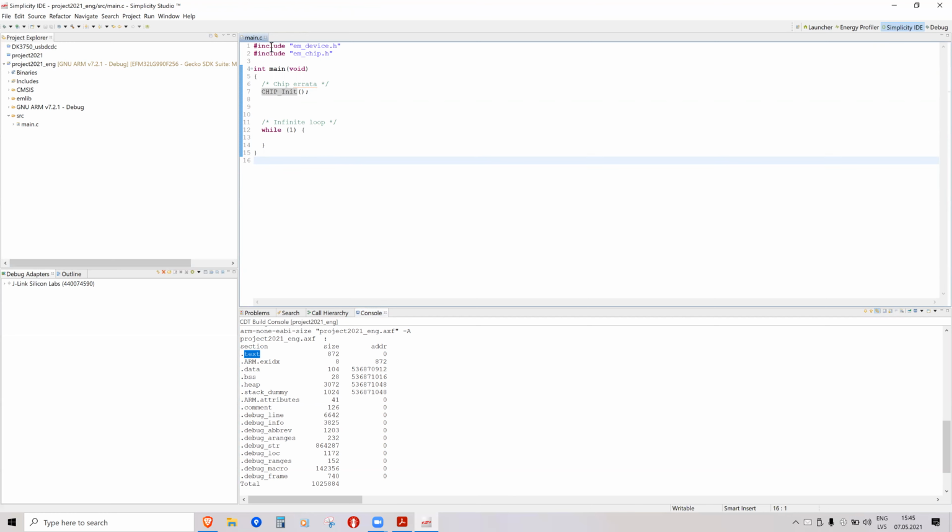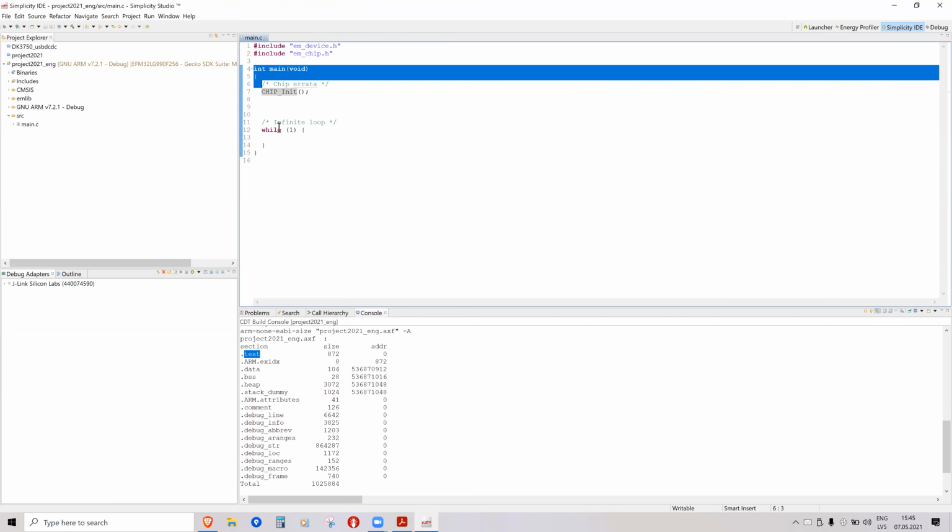It is because in the C programming language, there's this thing called startup code, which initializes the chip, initializes the stack pointer. It also sets all global variables to 0, all static variables to 0. It also copies RAM functions into RAM. So actually, before your main code is called, there are special things that the C program automatically does before going to your code.